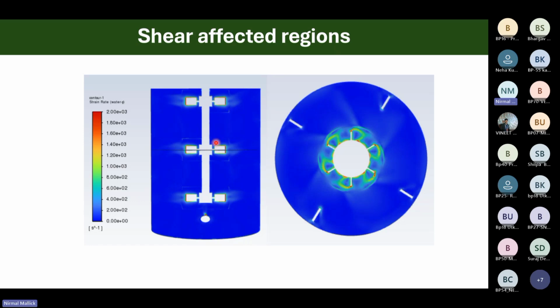So in this way, you can design your own reactor. You can design your own impellers for various purposes. Suppose you are able to design a better impeller blade for a mammalian reactor, which can go more than 500 or 600 rpm with less shear effect. That will be really good, which can increase the mass transfer coefficient, right?